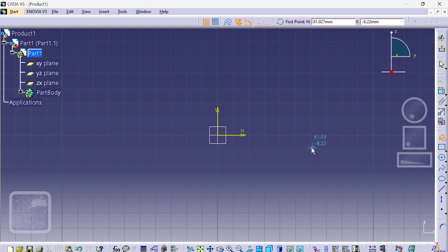Now you have to move your cursor to the origin and make sure you keep your object at the center or origin, so that you can create it much faster compared to offsetting your object. When you move your cursor to the origin, you will see two circles, one lighter and another darker. It means your cursor is exactly at the 0, 0 position. Then without moving your mouse, just left click. It will start creating the line.